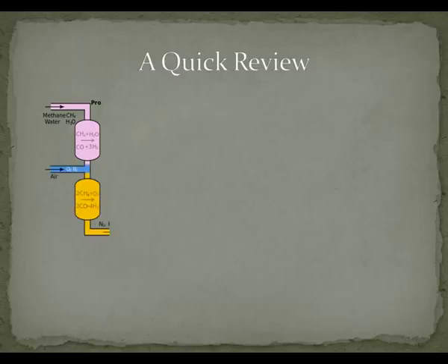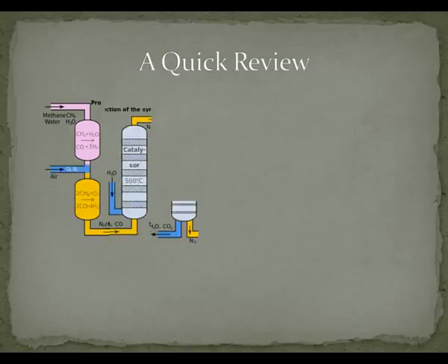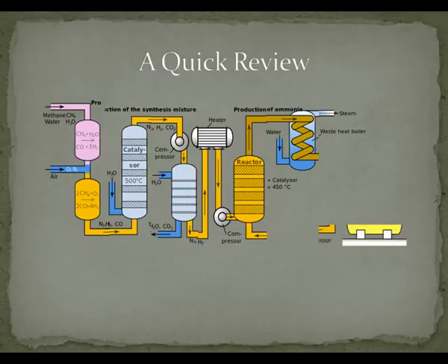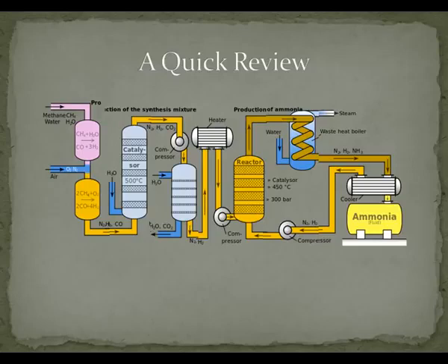The gas mixture is kept pressurized in a condenser, and ammonia is removed from the reaction vessel by cooling the mixture. Because of the hydrogen bonding between ammonia molecules, the ammonia condenses into a liquid while the nitrogen and hydrogen remain as gases. Ammonia is removed to shift the equilibrium toward the production of more ammonia. Once the ammonia is removed, the gases are recycled back to the reaction vessel in a continuous operation.